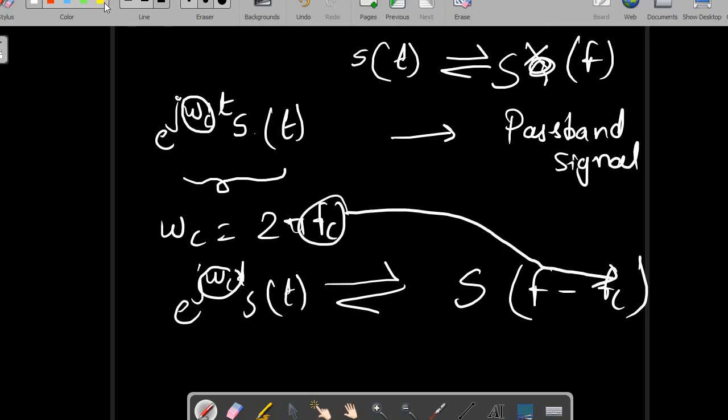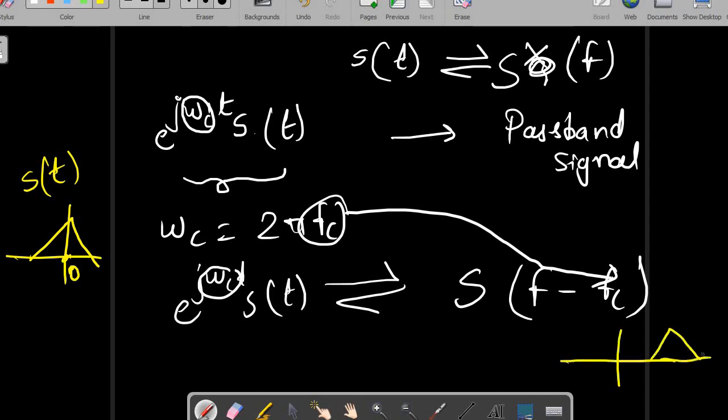As you can see, previously our s(t) signal was a baseband signal, so its center frequency was somewhere around DC, that is, frequency 0. A DC value has no frequency component, so it is centered around DC. But now, if we plot the pulse, it is centered somewhere around f_c.